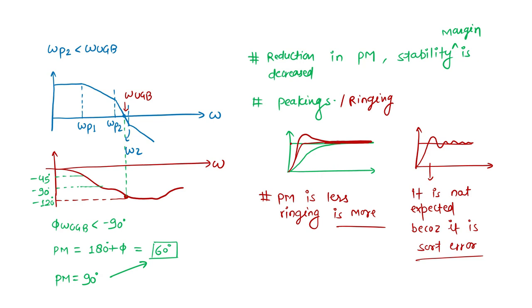In the coming video you will see the exact equation for the phase margin, how we relate it, and where the location of omega p2 and omega z should be. Minimum they should be at omega ugb, and why they are required, so that we can have the first order response till omega ugb. And if it is not like that, then we will see the possibilities.